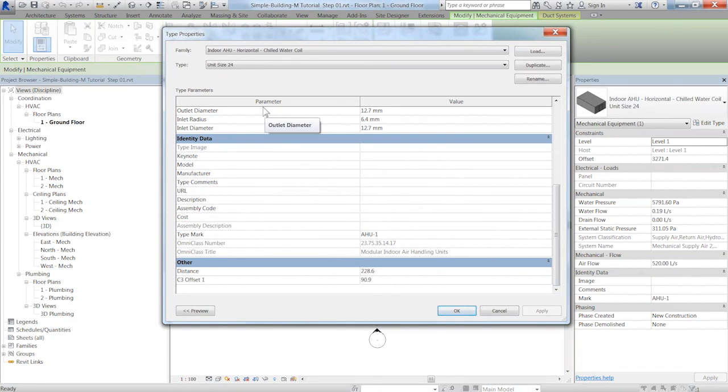Inside of Revit, just going back a few steps in case you're not too familiar, Revit is a 3D modeling tool, and everything inside of Revit is what we call a family. In other words, it's a very, very smart block. That means that all of the information that's required to create a BIM model is already built in to Revit. In addition to this, you can add further fields, or what we call parameters, to any of the family items to make sure that you get the information out that you want.